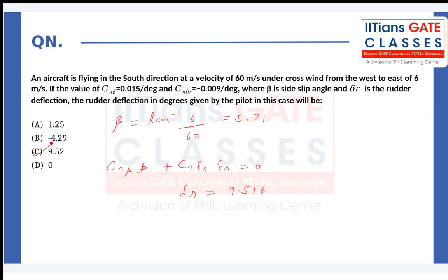Phugoid mode. Okay, yeah, I'll look at dynamic stability. So when you deflect the aileron, it does produce some amount of yaw, which is why you need to deflect the rudder to maintain it.